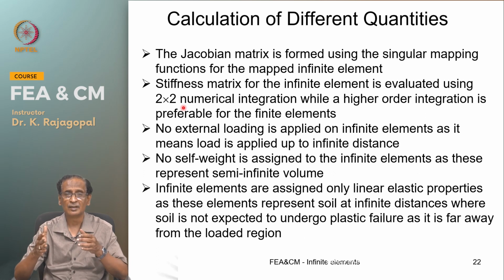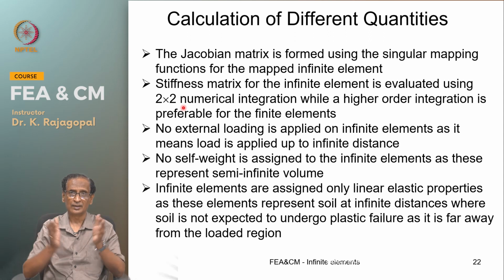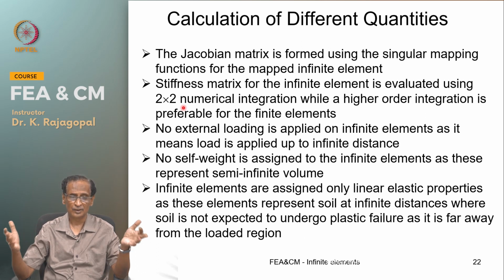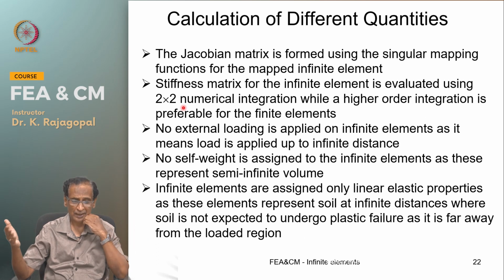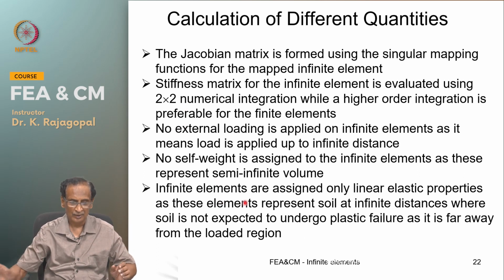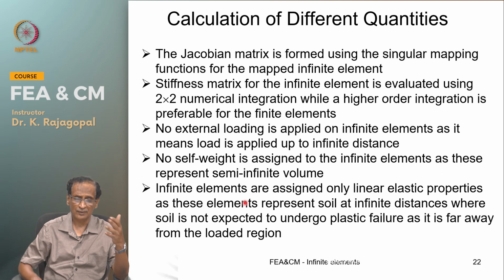That is not the reality, because our applied load on the surface may be spread over some distance, like 3 to 5 times the footing width, and beyond that the pressure is so small that you cannot have any failure. So, we make sure that all the infinite elements are assigned only linear elastic properties, so that you will not have any failure.